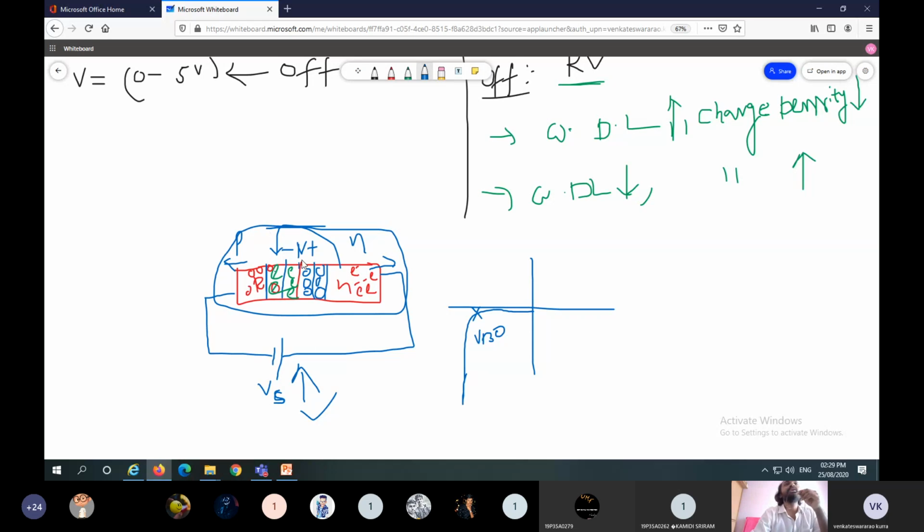So this can be avoided by decreasing charge density. If you decrease charge density, we can increase the rating of the device. Decreasing it means it acts as nearly an insulator, so it should be capable of blocking high voltage. And the width of the depletion layer also increases due to reverse bias condition.